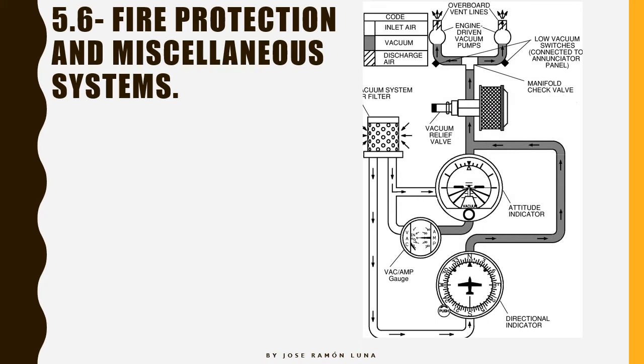This air is going to continue looking for the outside of the plane, and it's going to go out through the overboard vent lines. The air is going to go out of the airplane again after having moved these gyros required for working with these instruments.